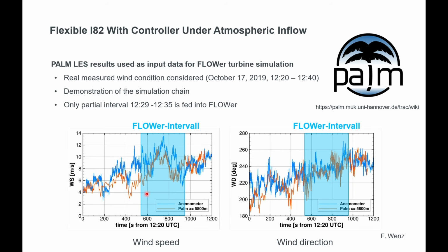And this time we used a scale-resolved precursor simulation with an LES code. In this case, it's PALM, developed by our colleagues in Hanover. And then they have a nice feature. They have a nudging approach. That means they can impose a source term in the simulation in order to urge the simulation to follow a certain time signal of the wind field.